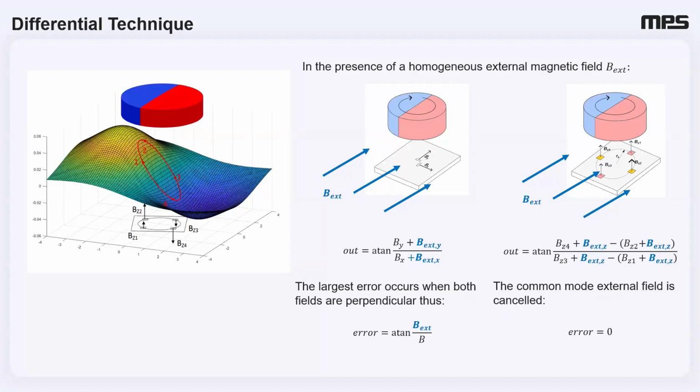What we can do instead of using these two vertical orthogonal Hall plates is use the planar Hall cells like we talked about early in the presentation. Before, the field came out, curled around, and we were sensing the in-plane portion of the field. This field still comes out and curls around, but now we're sensing the orthogonal component, because it's curling down and then back up. So for instance, this Hall plate, BX2, would see a field pointing downward, or a negative value. This one would have a positive value.